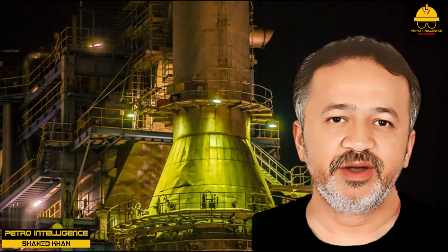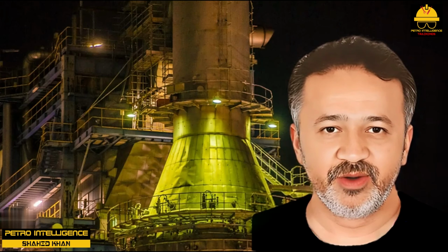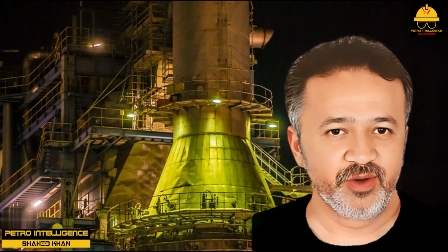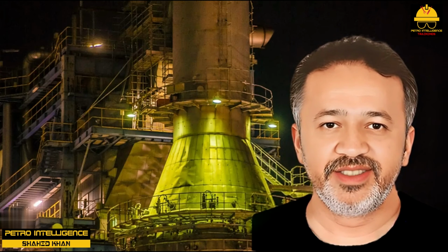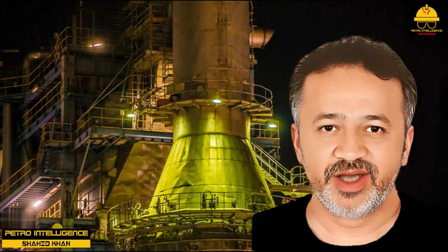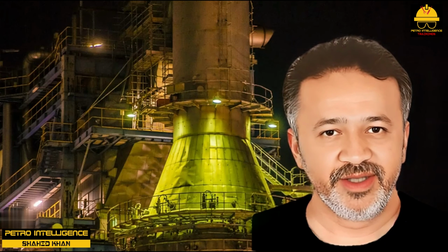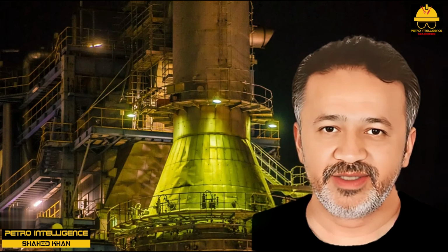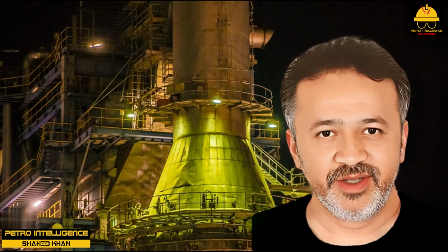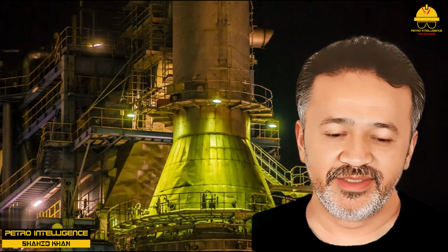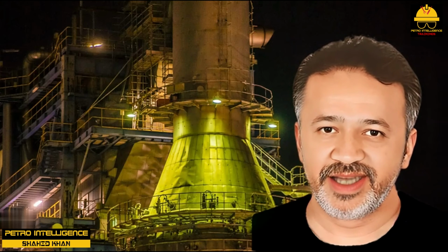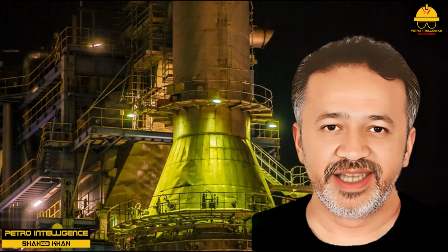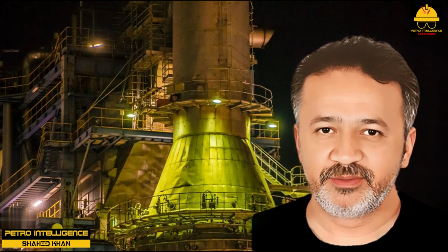Please note that it is not only bad practice but extremely dangerous to light main burners without the use of a properly installed pilot light. Butane torches, fireworks, torches consisting of gasoline-soaked rags on sticks, or residual heat in the furnace refractory do not provide a safe alternative to a properly installed pilot light. Please also note that fired equipment either without burner pilot lights or with extinguished burner pilot lights have been known to explode during operation, as the pilots, when lit, do provide some means of safely relighting or keeping main burners alight.